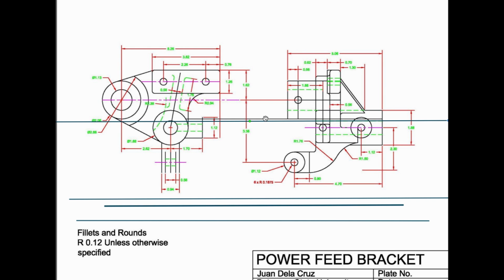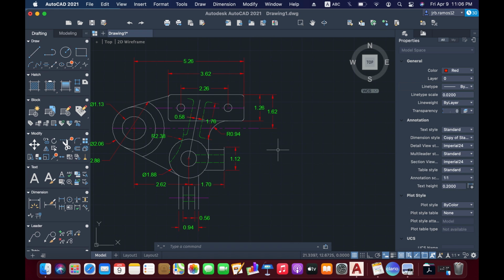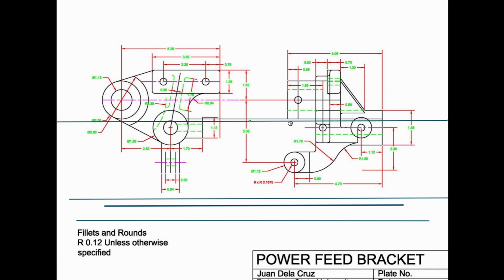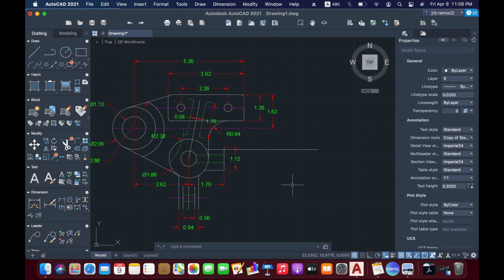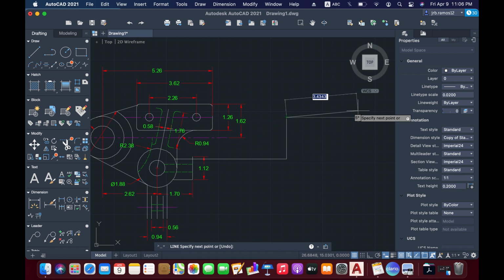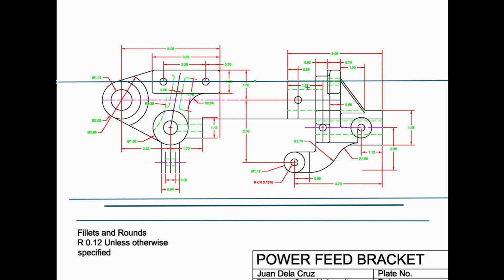Going to start here. So as you can see, it aligns. So I'm going to change first the property of my line, command line. Then from here, with a length of 4.5, enter. The next is, as you can see from the purple line, from here it aligns. So I'm going to do that line, and I'm going to trace it until here. Okay, and then going to put here with the length of 1.88.